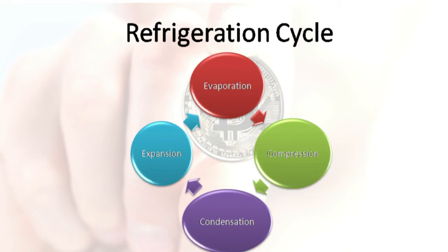So even though the condenser coil has cooled the refrigerant somewhat in the condensation stage by extracting the heat, as it exits the coil, it is still a relatively hot vapor, and too hot to directly cool the mining farm. The refrigerant is then piped through a system called an expansion valve.